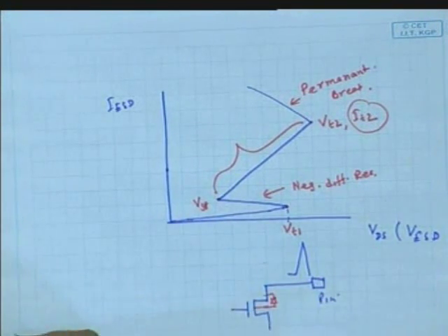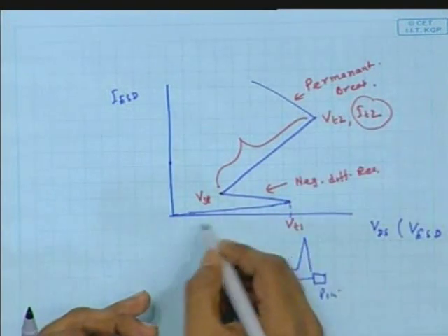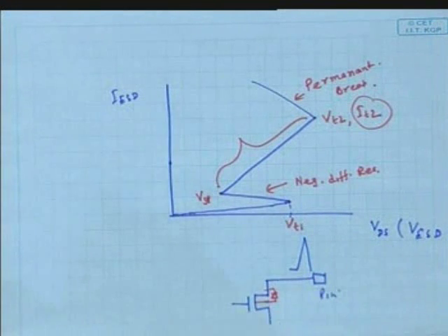So when people use the output buffer as a driver and as an ESD circuit, they characterize both. They characterize the MOS characteristics, and also the ESD phenomenon of the MOS, because it is helping both, right?